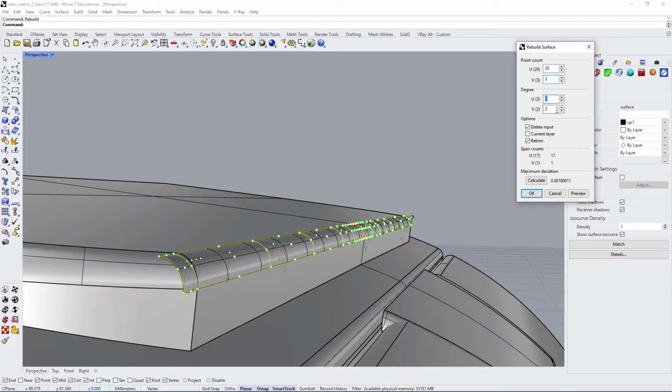And here you can kind of see the number. So on the left, you have the current number, and on the right, you've got the number you're using to modify. So here you have a degree 2 and a degree 3. So that tells me that this is a fillet, because degree 2 for something that is circular like this. Typically, when you see these numbers, they're a standard fillet that Rhino creates for you when you use the fillet command. So usually when you do a transitional surface, you'll see something that's higher than 2. You'll see, 3 is technically a transitional surface as well.